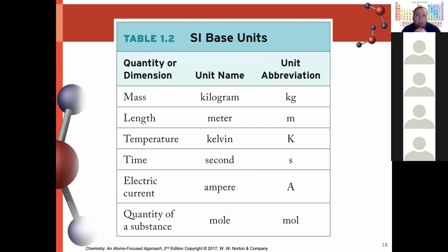There's always wattage, which is how much power is it going to use. Gives you an idea of, okay, there's a certain finite amount of power that I want, or that my circuit breaker is capable of using. And sometimes that's important. But more often than not, when you're buying light bulbs, you're interested in how bright is it going to make this room. And that's where candelas come in.